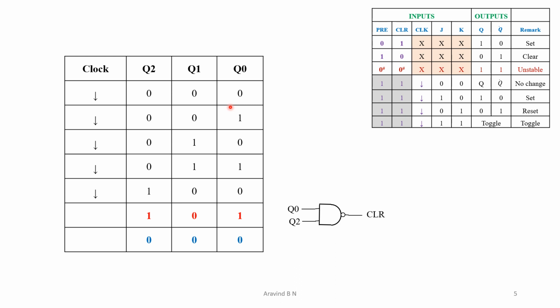And also you must make an observation that when we have connected Q0 and Q2, that means only the bits which are having the value 1 we have tapped, then there must be the same condition somewhere previous. That can be a consideration. But if we make an observation throughout, Q0 and Q2 are not simultaneously 1 before this particular point. You can make an observation of it.